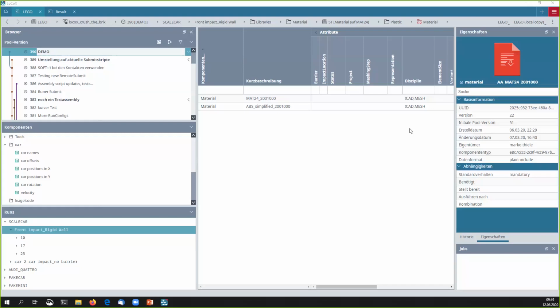And we also had issues with exceeding certain boundaries of numbering, because if you get into the range of 45 million elements, you have to be careful that you do not get beyond the 100 million number, because I think beyond that it cannot be handled by LS-DYNA. But also ANSA had some problems reading such big models. Probably they will get better.